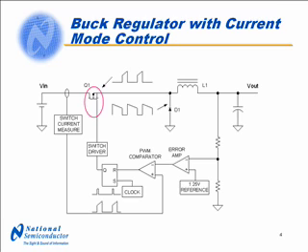When Q1 turns on, it immediately transfers the current which was flowing in the diode D1, and that's why there's an immediate step, or a pedestal, in the current profile of Q1. As Q1 continues to stay on, the current continues to ramp.